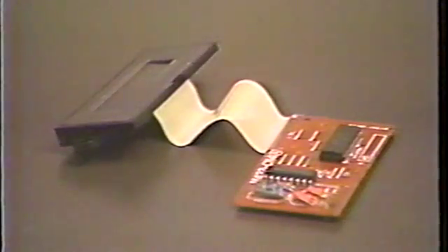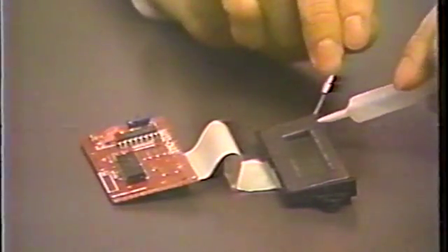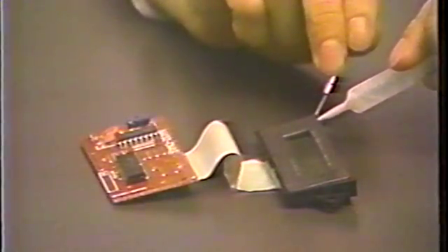Heat seal is used in installing the LCD. The LCD is connected to the PC board by a sheet called a heat seal. When LCD segments do not light, the cause can be peeling of the heat seal or a faulty LCD. The LCD is attached using double-faced tape, which may be difficult to detach in some cases. Applying alcohol can help make this relatively easy.